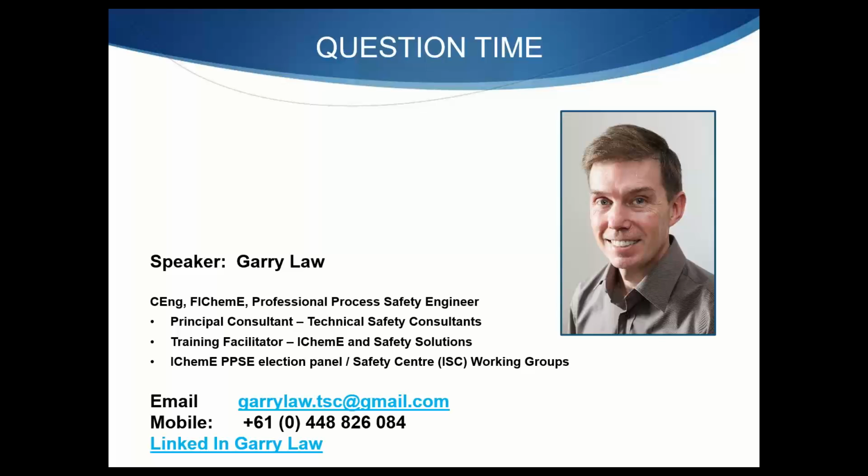Yeah. Well, we talk about this as start HAZOPs quite often. Double jeopardy means that between periods of maintenance, something might either fail and not be picked up, or it might have been locked out for some reason and not put back, so shelved or put into some sort of position that means it won't work when required. And that's not picked up until the next time you have an incident, unless you've done some testing in between. So in that case, it's not double jeopardy, because in the Buncefield example, I think they locked out the level trip. The fact the alarm didn't work was independent, but it was only one failure, really. Yes, they had the failure of filling too high, but once they'd had the failure on the alarm, nothing else was going to stop it. It was going to go over the top at that point. So that's why I think it's not double jeopardy in that particular case.